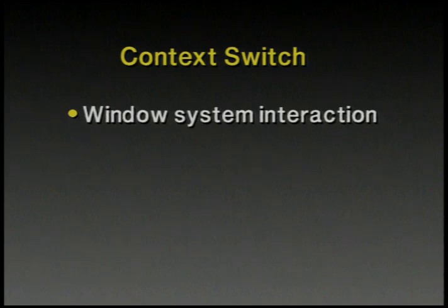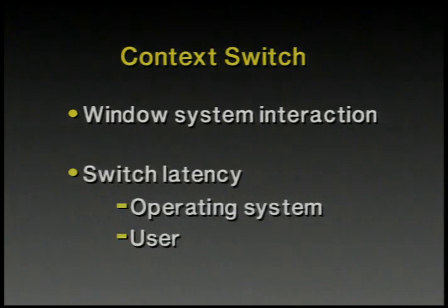Likewise, those large FIFOs that we put in there to make the load balance very nicely are also a huge amount of state that also have to be read out, swapped somewhere, and loaded back in when the context changes. If there are large context switch latencies, they affect the efficiency of the operating system. Obviously, just like the amount of time it takes to load and store the registers in the processor makes a difference for the operating system, a bulky context switch, like the amount of data required to operate on one of these parallel systems, can have a huge effect on the efficiency of the operating system. So it's important that the context switch time be minimized, and if it can't be eliminated, it's useful to arrange the system so that the switch happens in parallel with the processor doing whatever it does. So you first work to make the context switch as fast as possible, and then make sure that the implementation allows the switch to take place largely in parallel with the operation of the general purpose processor.